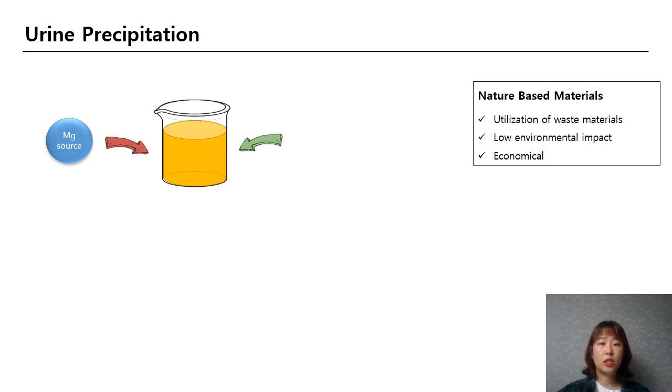Chemical precipitation is one method that can separate nitrogen and phosphate from the urine. Struvite is the most common chemical product, made by adding a magnesium source to urine. Magnesium is added to the urine and stirred to crystallize magnesium, phosphate, and ammonia into a 1:1:1 ratio of struvite, to concentrate phosphorus and nitrogen in a small volume.